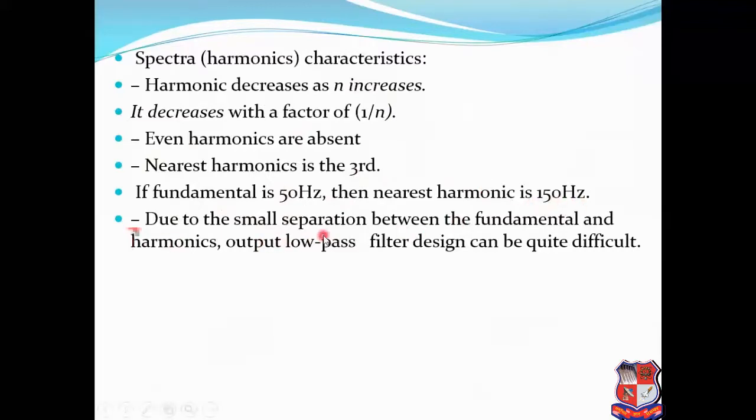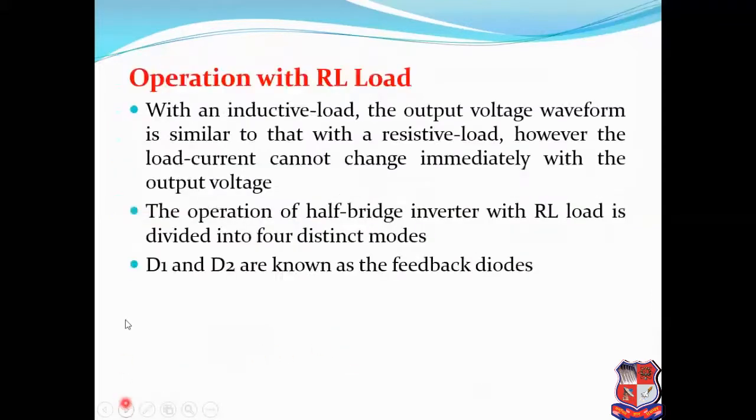Due to the small separation between the fundamental and the harmonic component, if we want to eliminate or mitigate, or filter out the lower order harmonics, then we have to design a low pass filter for this purpose, to filter out the harmonic content.